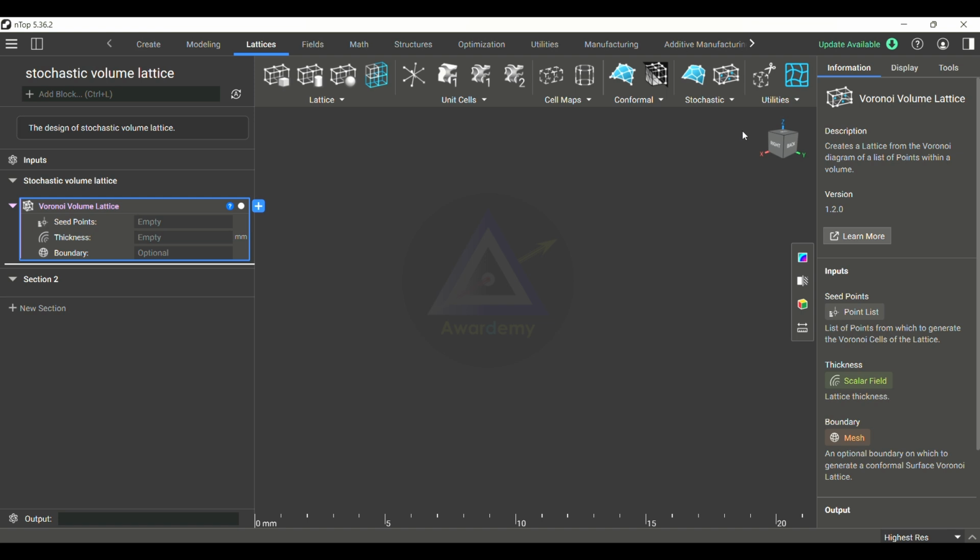With respect to each point, one volume will be generated with a boundary, similar to a mesh element, like a tetrahedral mesh or a cubical quad mesh. The body can be a cube, cylinder, cone, sphere, torus or anything. Within the boundary of the body we distribute some points, and considering these points, we are able to generate our particular Voronoi lattice structure.